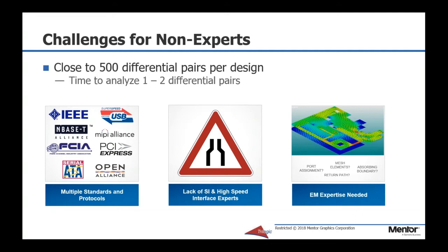Finally, SerDes channel analysis and design requires electromagnetic expertise. Some design teams do not have SI or EM experts in-house, so the additional burden of generating S-parameter models that accurately represent the PCB design is borne by the hardware design engineer.